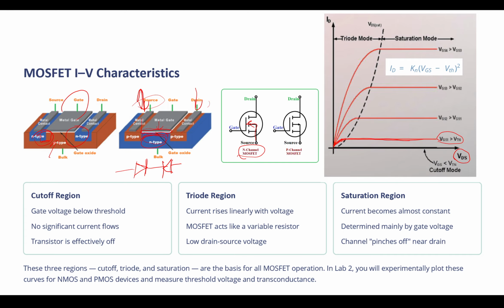Why is that? The concept that we talked about. We have a channel. If we have a specific width of the channel, that means we have a specific capacity of conducting current. When we occupy the whole channel, it doesn't matter how much VDS you force to the transistor, it doesn't have the capacity to conduct more. So it gets saturated.